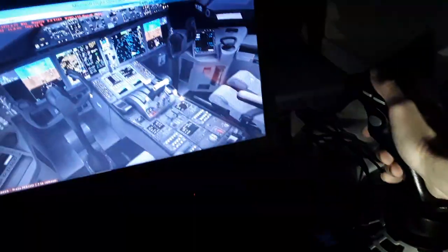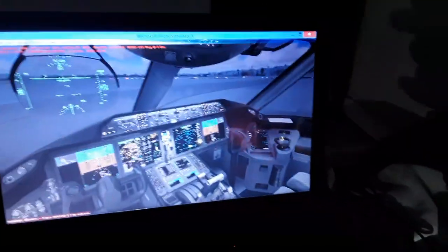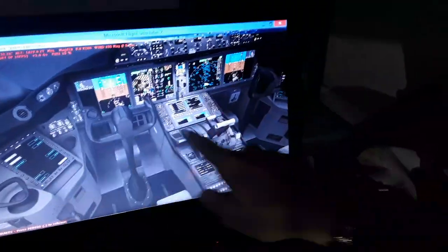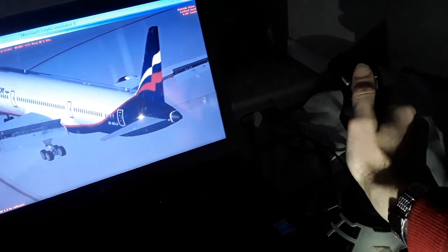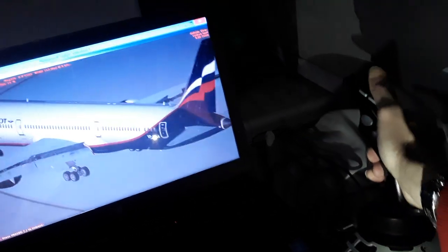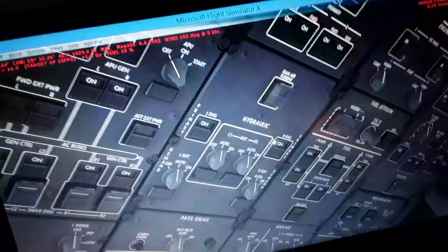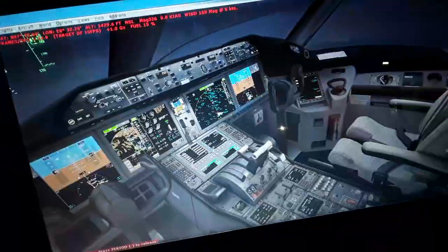You see here, when you move the flight controls, you have electric control using the flight control computers, but you have the hydraulic actuators also for the rudder pedals, nose wheel steering, thrust reverse, landing gear extend and retract, parking brakes. So when you move the tail up and down, or the rudder, or the ailerons, spoilers, flaps, speed brakes, you have hydraulic fluid tanks to pressurize over here. You can see, you have also the pumps, demand and primary, which are engine driven or electric driven.